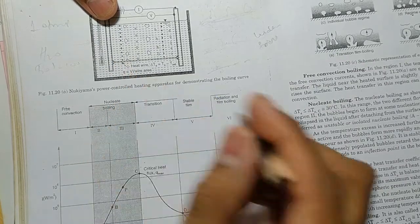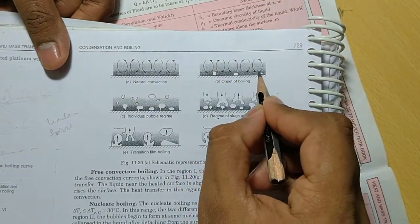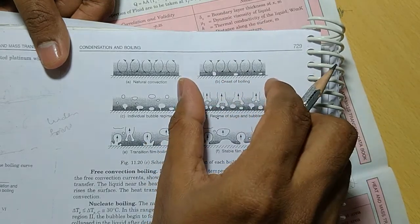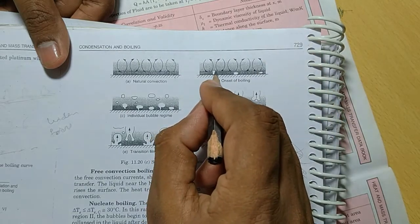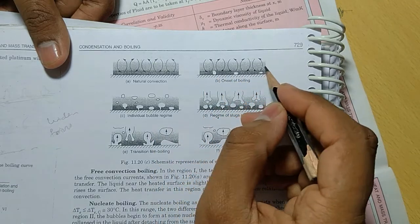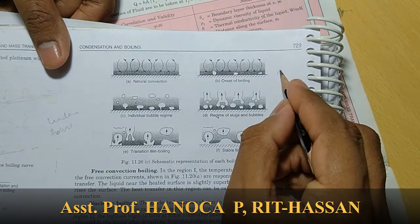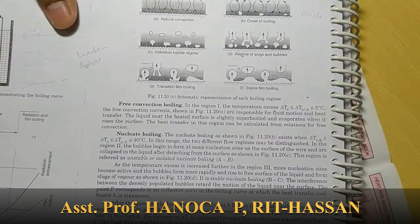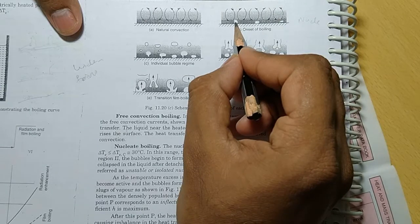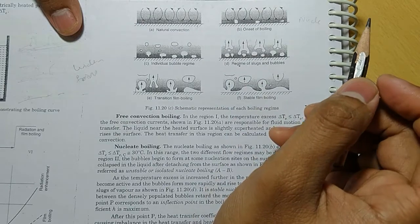For a particular temperature, bubble formation takes place at some parts. This is the complete electrical heater surface, one small area. At a few points, bubbling of the water from the surface takes place. That you are going to call nucleation. In a few particular favorable places, the bubbling starts. That formation of bubbles is what you call nucleation.